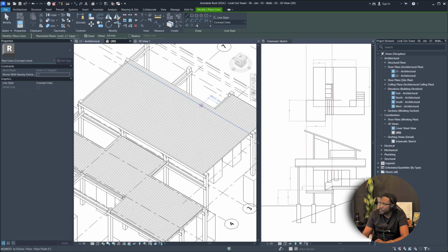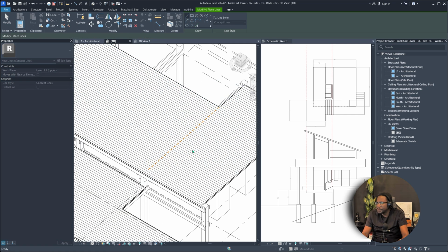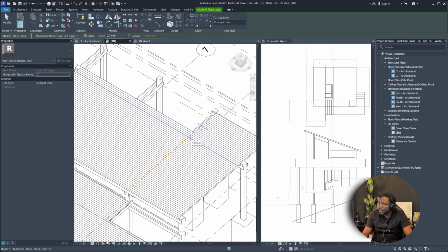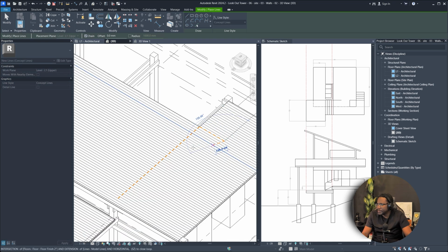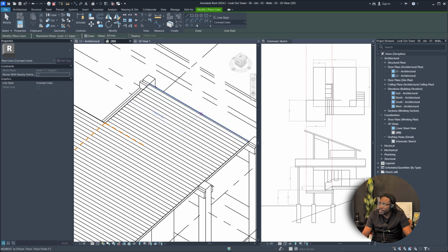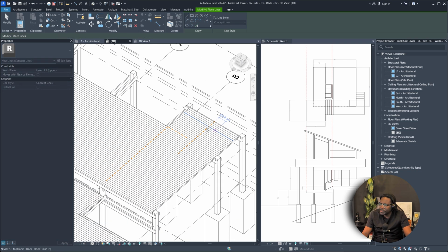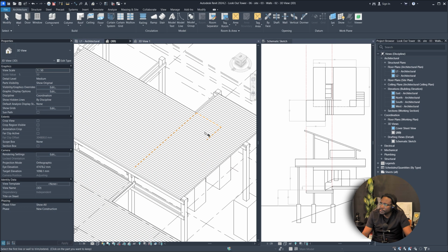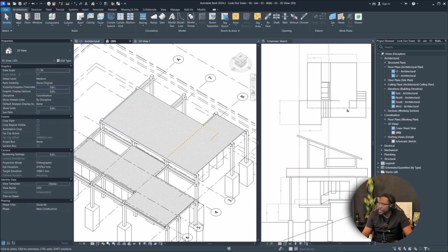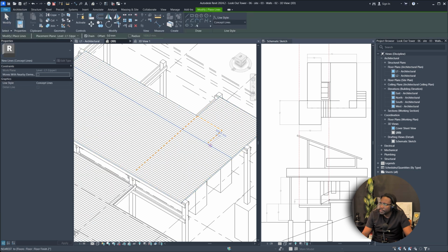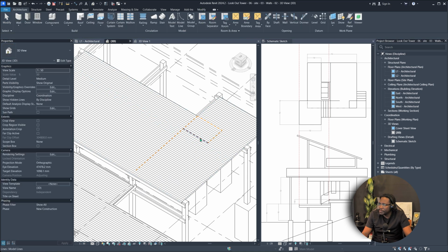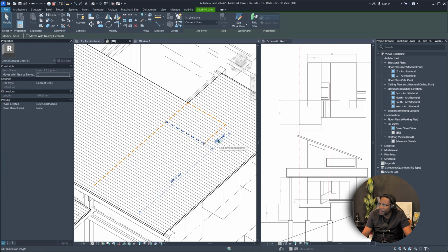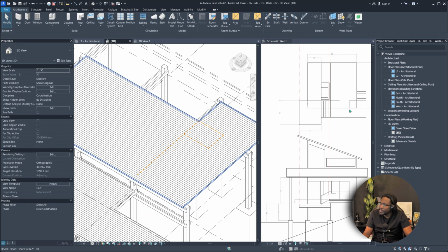So based on what we have here, this is pretty much going to be where our walls will be. And then we have this element that's coming out like that. It's probably going to be in the center of this wall here. So I'm going to put a mark here, and then I'm going to use the trim tool to trim up this wall here. All right. Then, that's this little area here that I'm doing. Let's join this back here. Let's see how big this is. This is about 2 feet. So let's make it, I think 2 is enough. Yeah, let's make it 650 millimeters. Yeah, there we go. So that's this area right here.